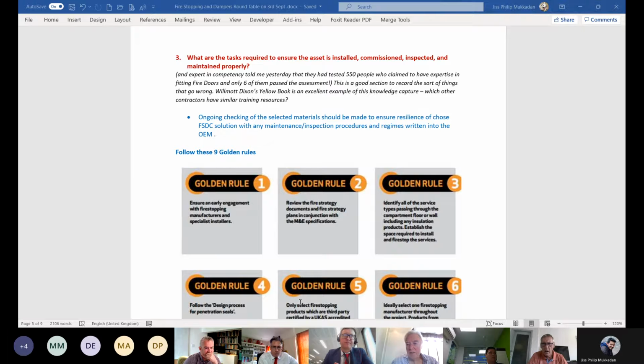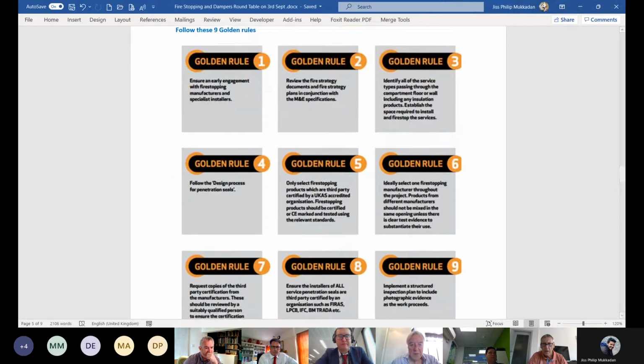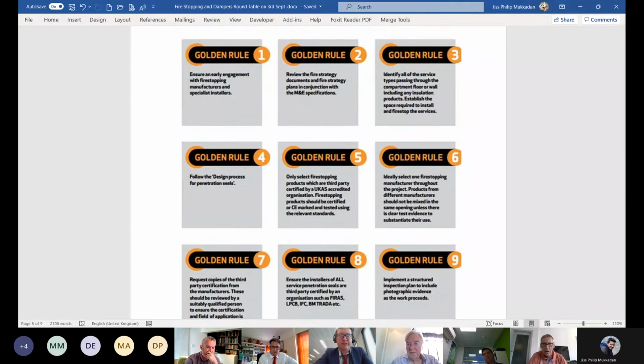So these golden rules are ones that Joe Cilia has provided, and they come from the book, like the parts 3 and 4. If I give you an example for fire dampers, you'd say always check the building movement and tolerance, because a damper doesn't pick up deflection. Generally, the structure does. There are some deflection head dampers on the market, but generally the wall picks up the deflection, so you can end up with 250, 300 mil deflection heads, which don't get accounted for.